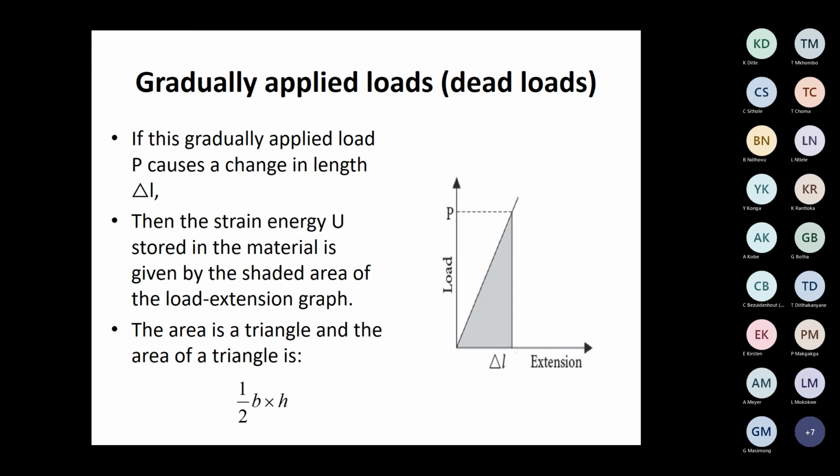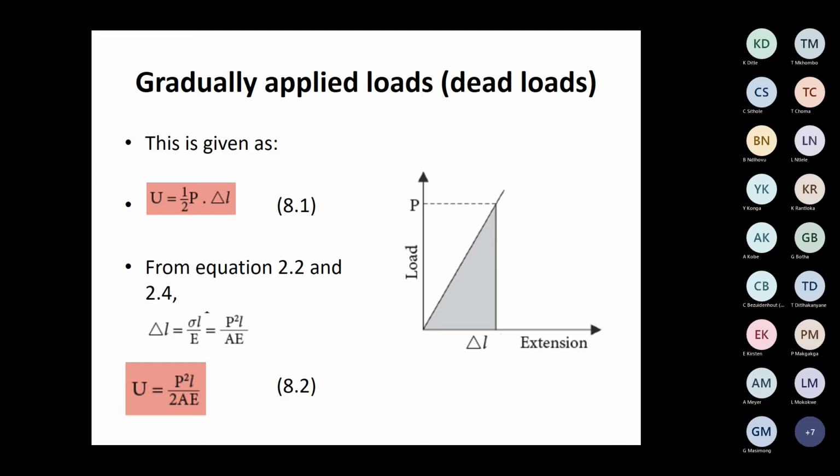My base is my change in length, and my height is my load. So the strain energy is half load times change in length. Important: this formula is for a single load, not a double one. That one we come to later in theory. It is only a single one with a load down there.